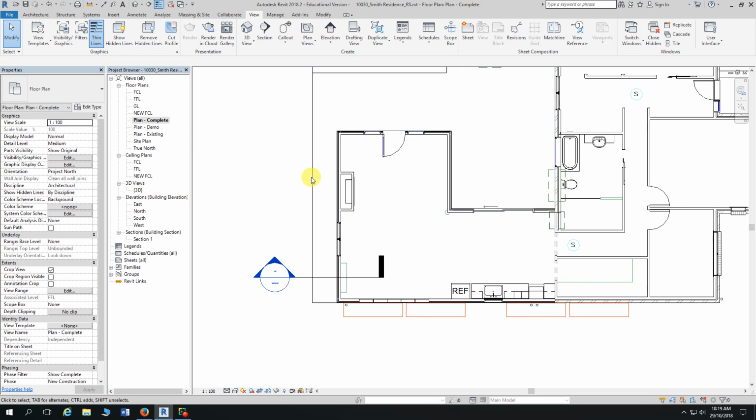the deck here, there are 4 90 by 90 posts. We can't see them at the moment because they are still part of the AutoCAD drawing, which is underneath the current deck. So in order to see each of the 4 rectangles, the 90 by 90, what do we have to do? Change the visual style to wireframe. So I'll get you to do that.